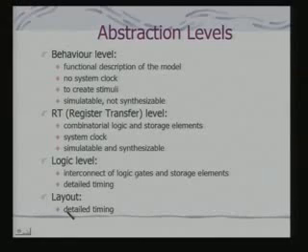If it is a soft core, it can be a pure VHDL specification. So, when you want to add functionality to that processor, depending on your system design, you add on a module to the VHDL specification of the processor. Okay. So, you have got an enhanced hardware, fine. If it is an absolute hardware core, that means you may have the layout level design available with you. So, you add functionality to the system and maybe design an ASIC or an ASIP as the case may be.